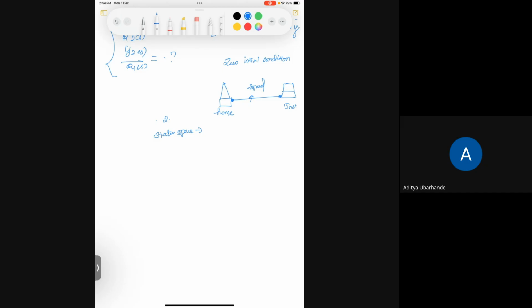I will just list out the things in words. This is transfer function, SS is state space. Transfer function is okay for SISO and for LTI systems, easy to represent single input, single output, easy to represent LTI systems. And state space is more feasible to represent MIMO systems. SISO can also be done, but doing MIMO is also easy here.